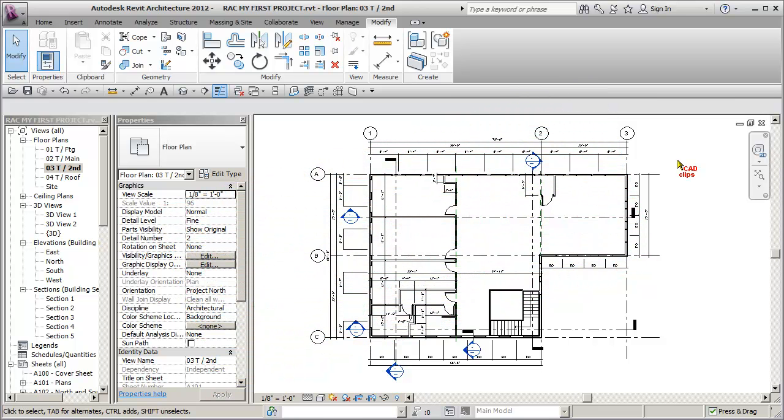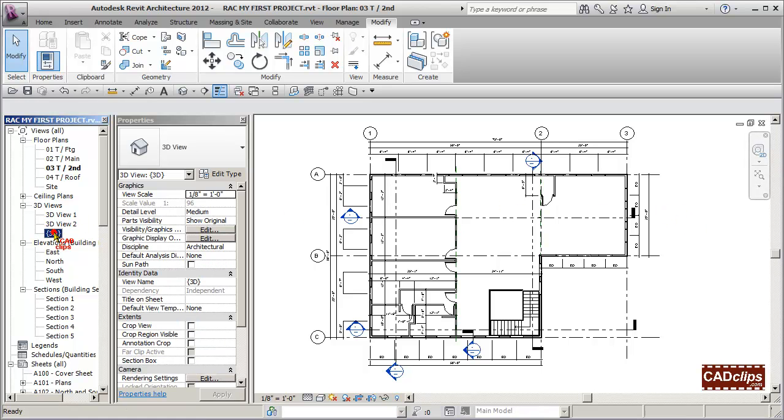And here's a fun lesson on 3D sections and plans. A lot of people don't know you can do this in Revit. So what we're going to do is create some new 3D plans based on the default 3D view. We'll duplicate them and then we'll apply plan views and sections, etc. to those 3D views, and the effect will be really neat. It'll have a 3D sectional box.